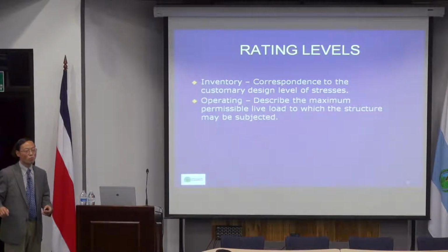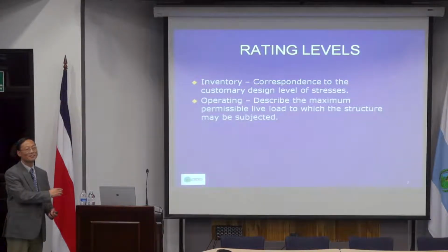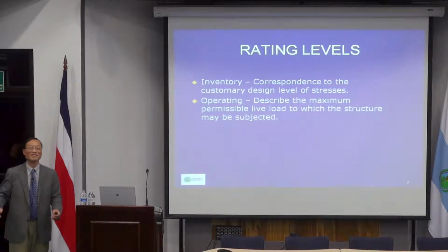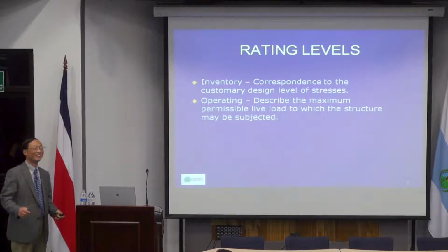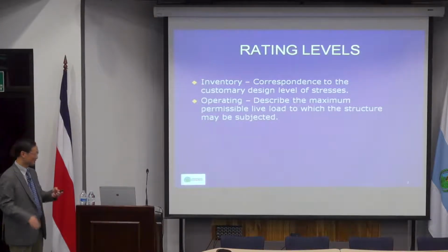That level will make most bridges seem safe on paper, but in reality, it's still safe. A bridge has big redundancies, and if any member simply yields, it does not really cause any problem. And also because loading is very transient, it just comes and goes, not like buildings, where people sit for many, many hours. So that's why it's not a big issue when we have a dual system.